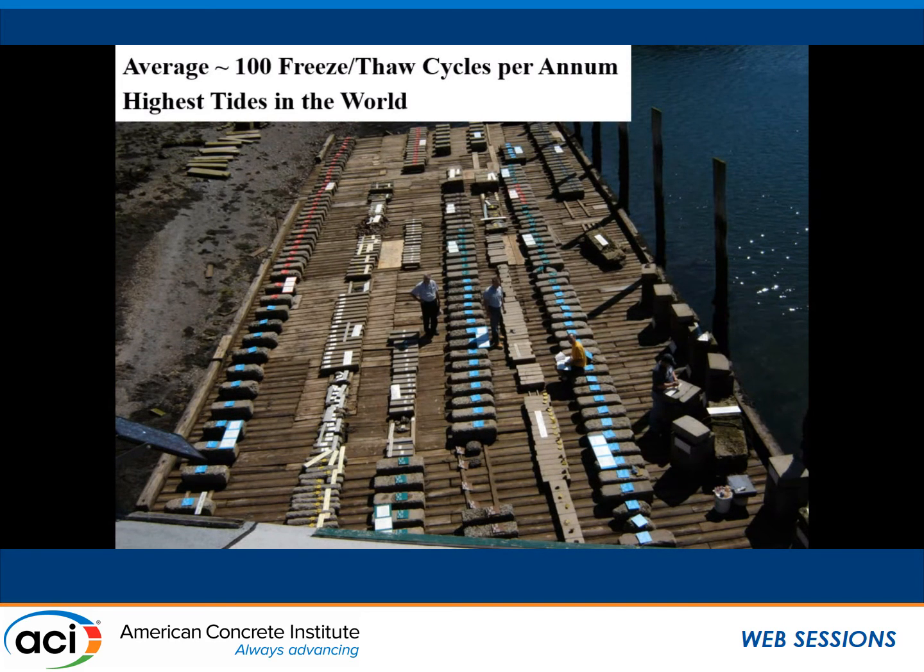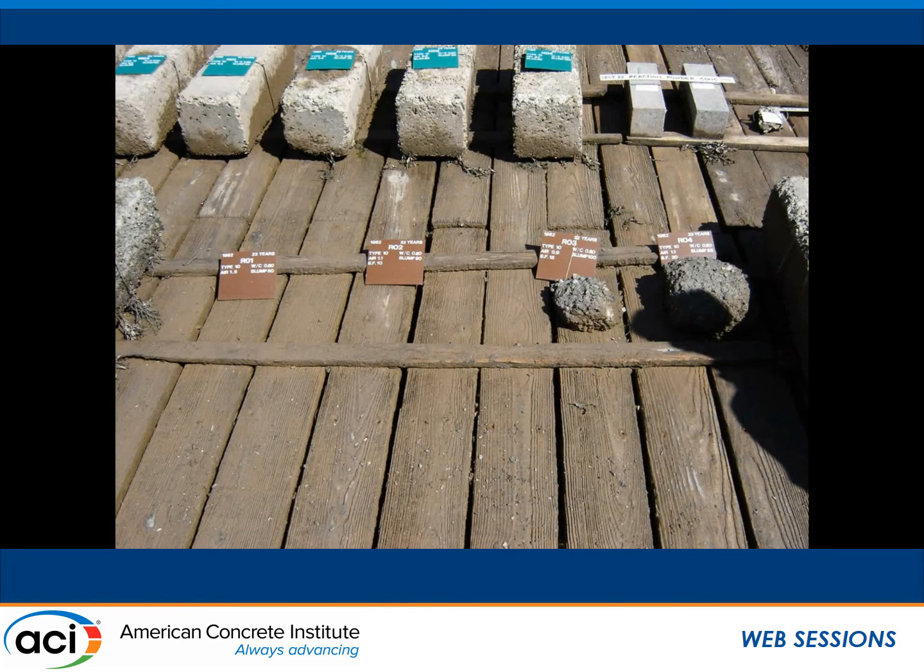Over the past 60 years or so, literally hundreds of different programs put concrete on the site to study marine performance. I just wanted to show you in the 90s, and since this presentation goes back to the 90s, this is relevant, there was some discussion about the role of air entrainment in high-performance concrete. People were saying if you had really high-performance concrete, 0.33 water-cement ratio with silica fume, you didn't need air, right? I don't know if people remember that, but there was a great deal of debate. Well, that's what happened to the non-air entrained high-performance concrete at Treat Island.